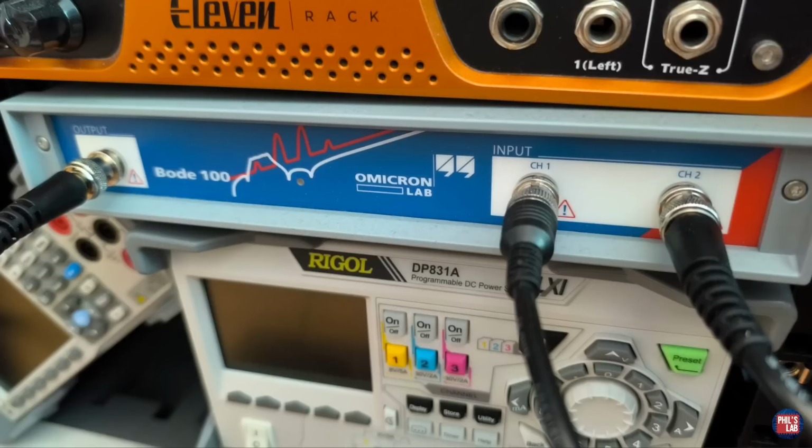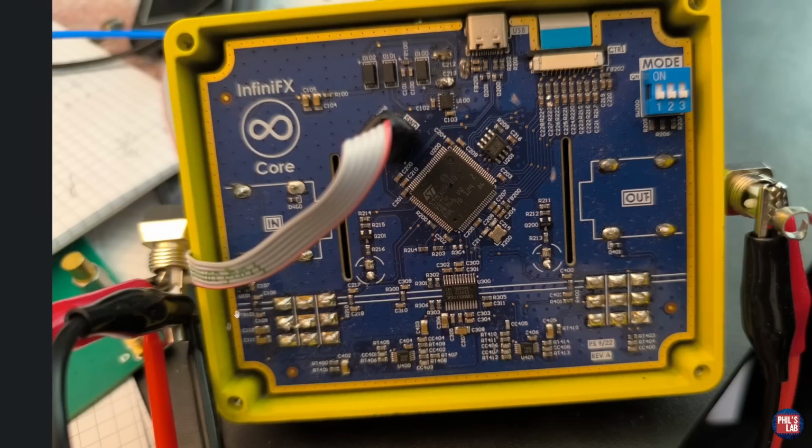In terms of connectivity, I'm going to be doing a transfer function measurement, so a gain phase measurement. We need to connect up the output of the Bode 100 to the input of this effects platform. Channel 1 of the Bode 100 will also connect then to the input of our digital guitar effects platform, and the channel 2 input will connect to the output of our guitar effects platform. And here, just a rough image of what's going on. I've got my Bode 100 output and Bode 100 channel 1 input connected to the input of my pedal, the Bode 100 channel 2 input connected to the output of the pedal. And this lets us then extract gain and phase information because we're measuring the input, we're measuring the output, and we're applying a stimulus to the input. And I'm programming the device using a Segger J-Link via Cortex debug and a Tag-Connect TC2030 programming header.